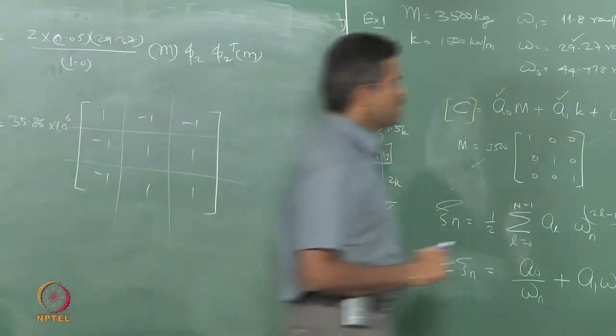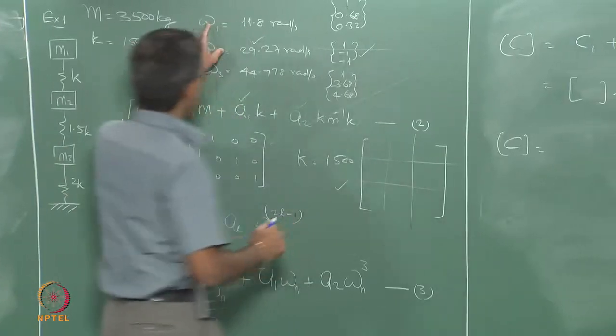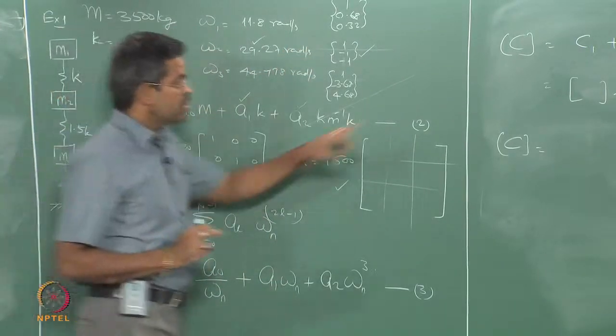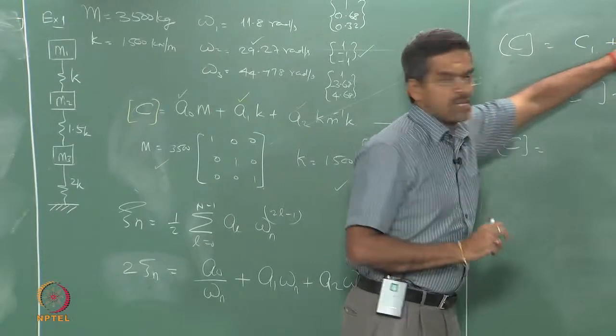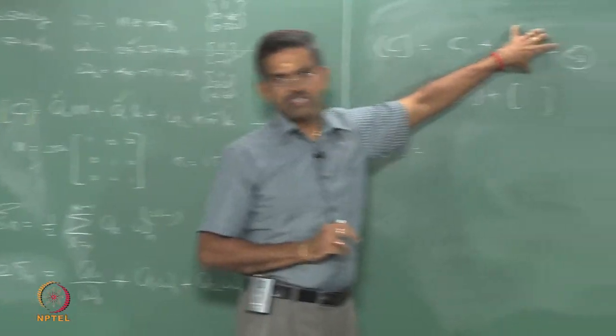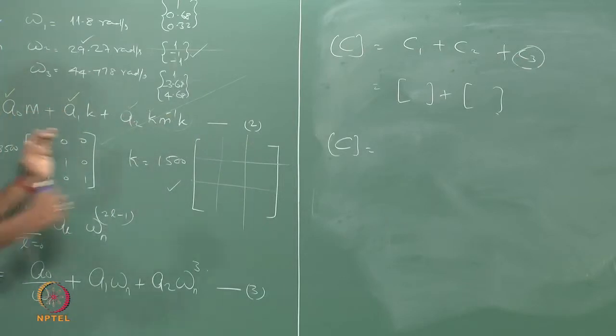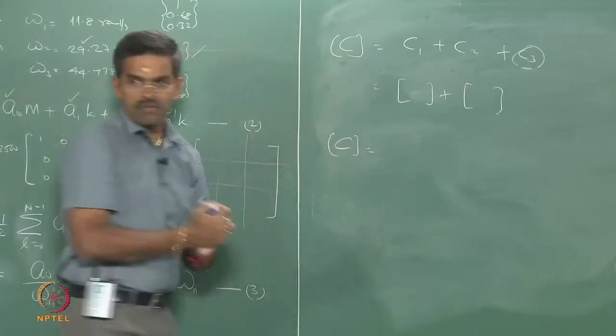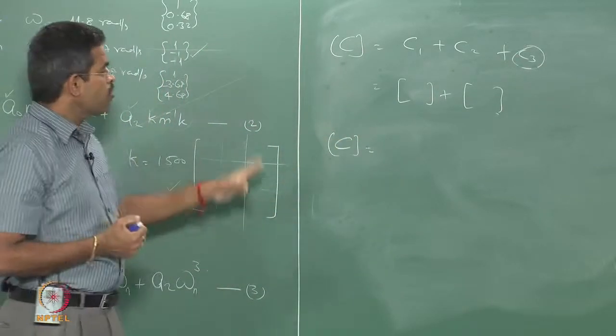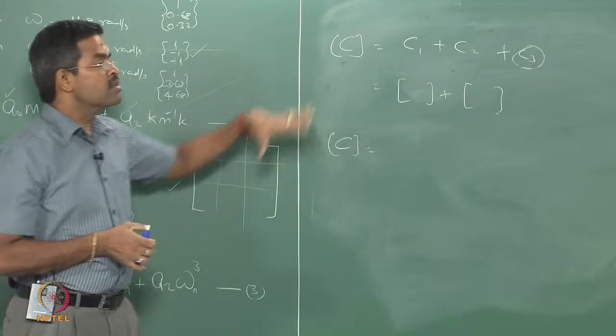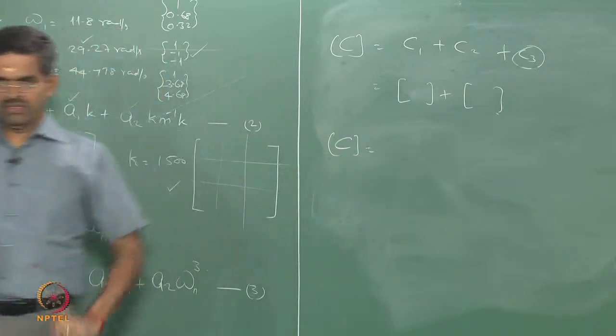Now answer me. It has got 3 degrees of freedom, there are 3 frequencies and 3 mode shapes. But C has only contribution in the first and second mode shapes only. What does it mean? Why C3 is not present here? What does it conclude? This C matrix will conclude that the contribution of damping from the third mode is insignificant.